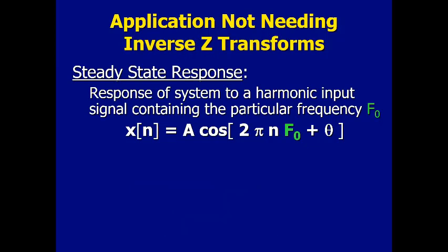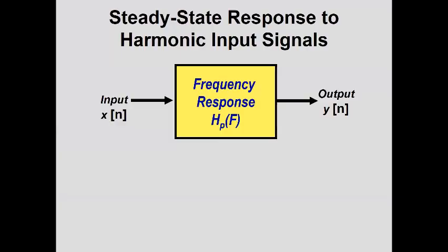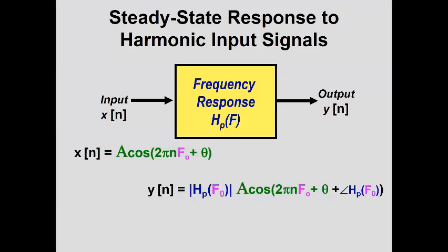We'd like to do that again, but we don't have the frequency response exactly available to us. If we did, we know we just take that original signal. When it goes out through the system, it comes back with the same form. The system can't change its shape. It's still a cosine or sine. It can't change its frequency as long as it doesn't alias.